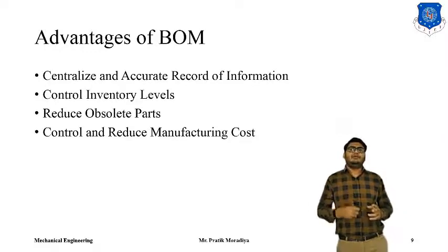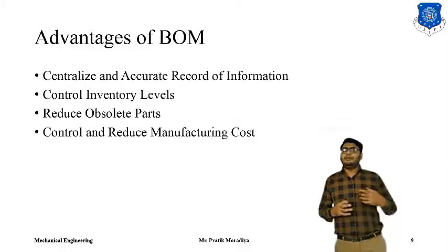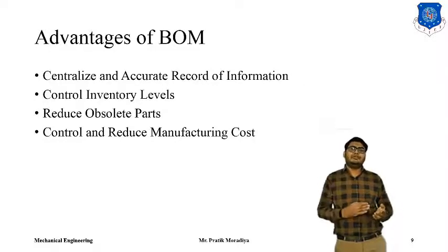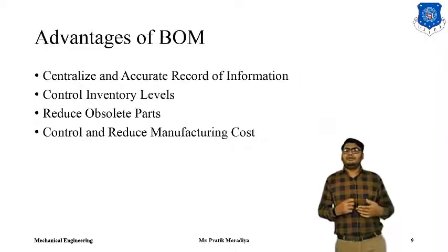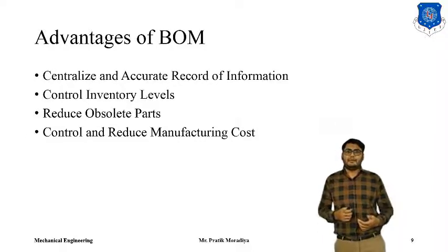How will it help us reduce the manufacturing cost? Suppose you want to change your design and after changing the design you make a bill of material and you compare both the bills of material for the old design and the new design. If your new design has less manufacturing cost, then you are saving a certain amount of money. If your new design has higher manufacturing cost, you will rethink your design strategy. You will make sure that you come up with a design which can be made with less cost.